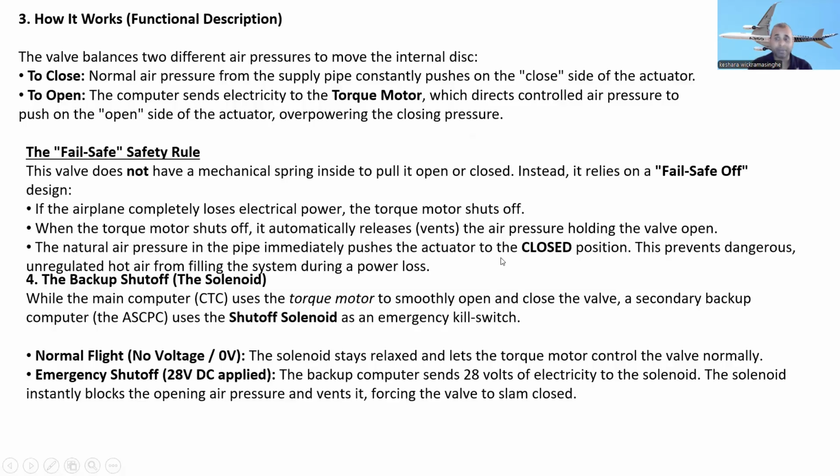Okay, what happens if the torque motor is shut off? At this time, the natural air pressure in the pipe immediately pushes the actuator to the close position. This prevents dangerous unregulated hot air from filling the system during power loss.